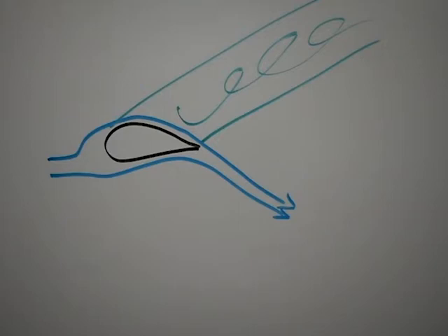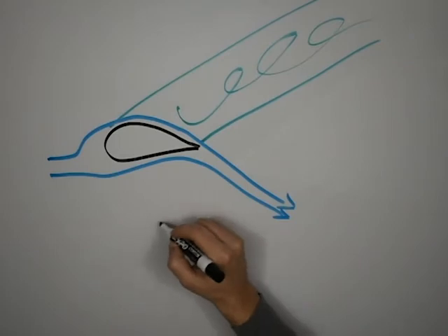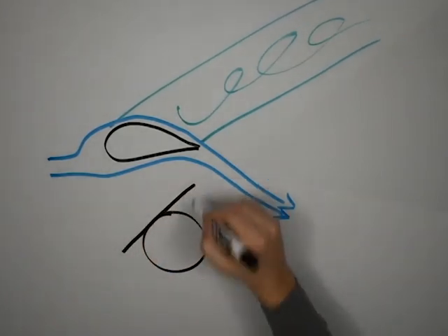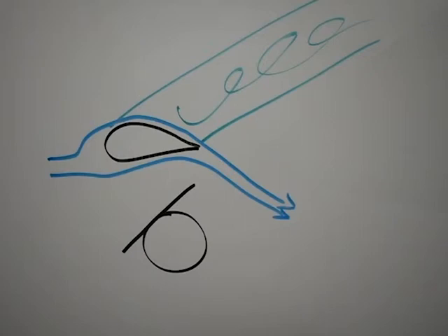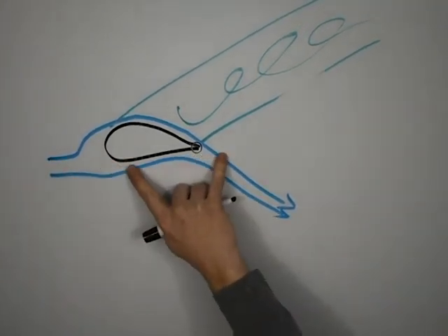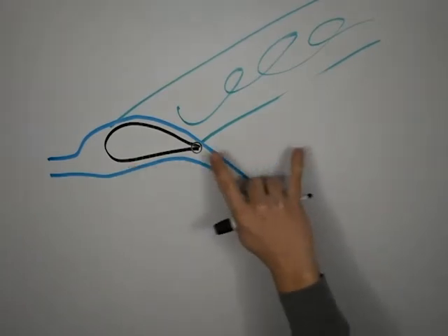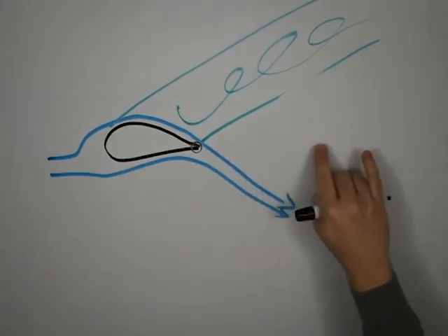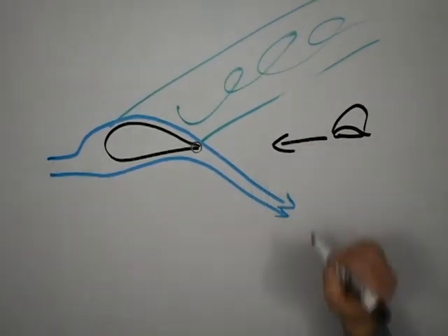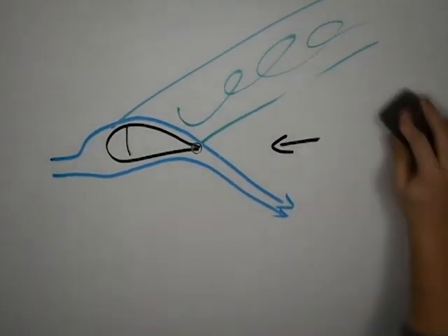What is a tangent line? Well, I'm glad you asked. If you draw a circle and then you have a straight line that only touches one point of that circle, that's a tangent line for that point of the circle. Using this area we laid out with the tangent line in that diagram I showed you from Raymer's book, we opted to put our tail 2 1/4 main wing chords behind the quarter chord position of our main wing, which works out to be 11.5 inches.